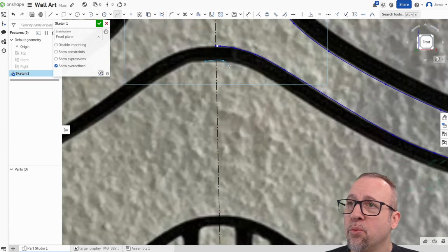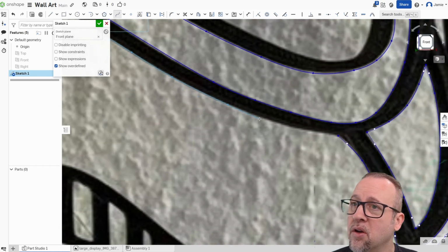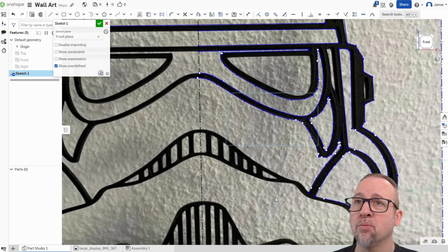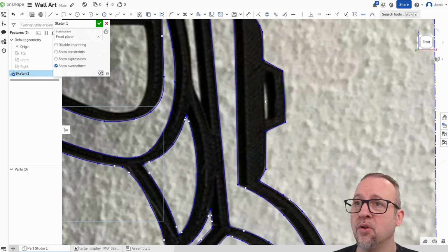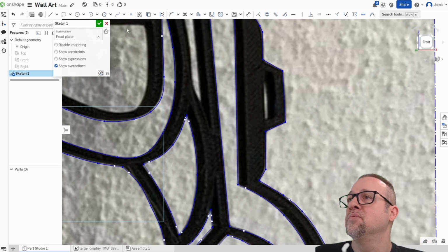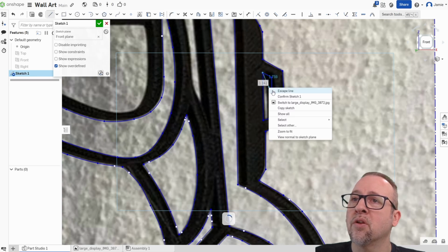We're going to start here, go past it. We'll clean it up after. No problems. Okay, so we right click spline, finish that spline. We're getting pretty close. I'm going to add this little feature right here. Since this looks like it's not real good, I'm going to fix this a little bit. So I'm going to put a square. We're going to do a straight line here, and a trapezoidal shape. Okay, right click, escape.